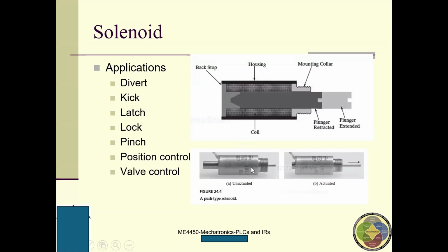And how can we accomplish this? I can just open a hole here and put this pole on this side. You agree? And then I can have push. This is called a push type solenoid. But this one is a pull type. It depends on how you use it. Understand, guys? I might ask you how to change from a pull type to a push type. You can just open a hole from the backstop and put a pole there.